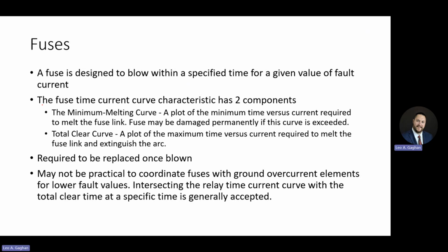And the other challenge with fuses compared to some other options is fuses operate on phase current, right? We have one on phase A, phase B, phase C. They operate once we get up above phase current. We don't want them to operate on normal load, because then you're going to lose power.